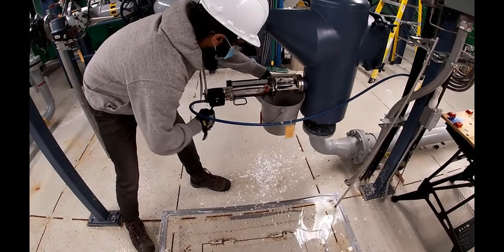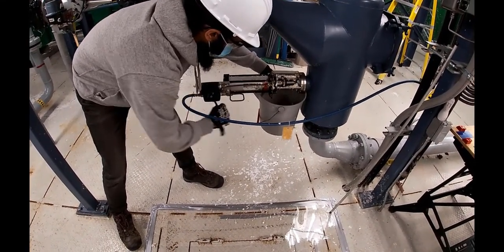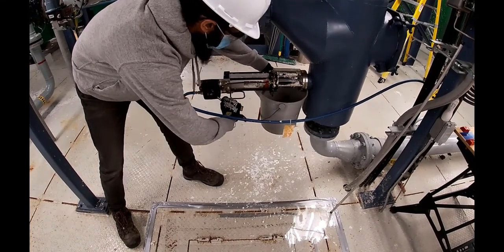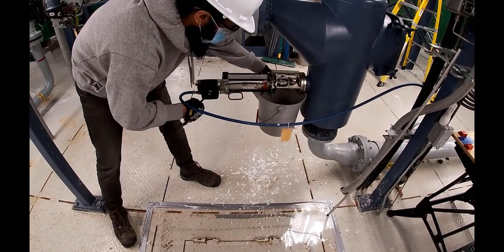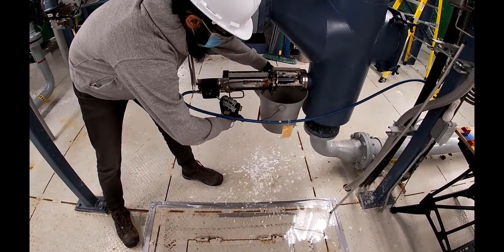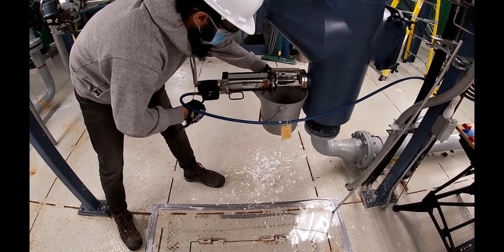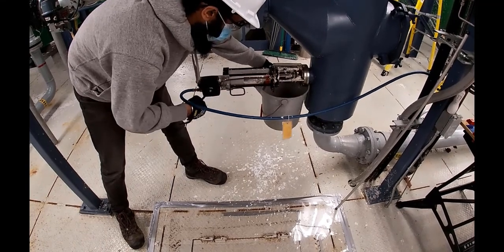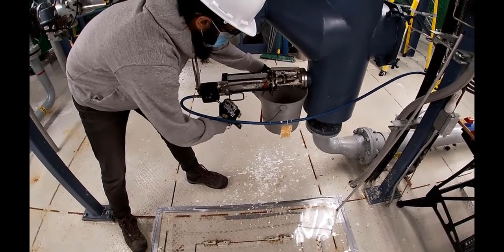So you can see that the stock is being brought in its little sample, and it's getting the right water fiber mixture ratio out of the center of the inlet through the consistency meter. And he's going to basically get about a quarter of a bucket. And once he's got that, then we'll go do a consistency test on it. Okay, that should do it.